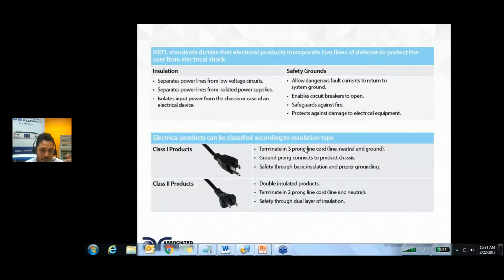Somehow, current is now shorted back to the return, and my transformer inside my hipot tester, which can usually only do 10, 20, 30 milliamps, is now seeing this short asking for way more current than it can provide. So it gets put in a state of overpower protection.